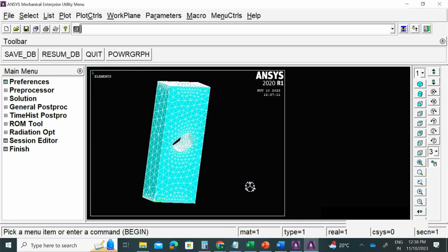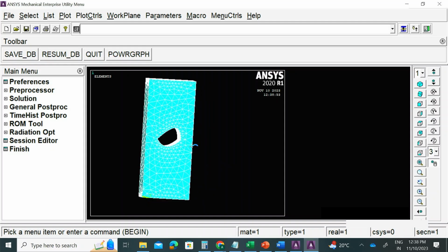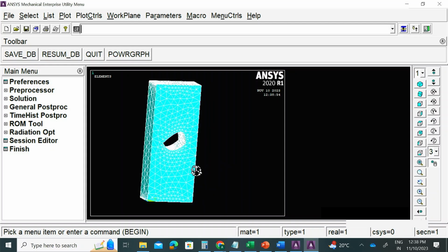Okay, so this is where we were. We had developed a sample model with a particular wound shape. This wound geometry was created through the bottoms up approach, and then we had created a set of splines, and based on that the area was subtracted from the almost rectangular area, and then we had extruded the entire sample. So we had learned about all the modeling techniques, the operating techniques, and how to do the meshing.